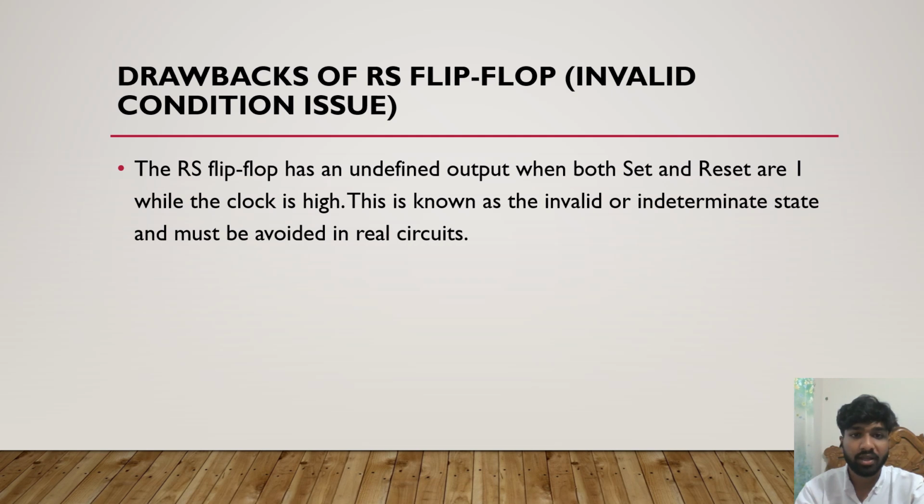Let's know the drawbacks of RS flip-flop, that means invalid condition issue. The RS flip-flop has an undefined output when both set and reset are 1 while the clock is high. This is known as the invalid or indeterminate state and must be avoided in real circuits.